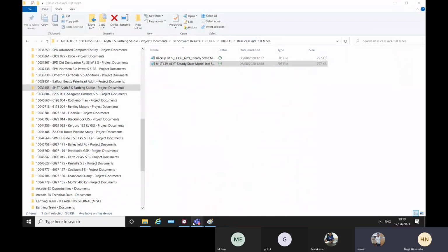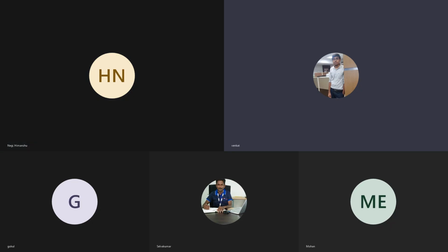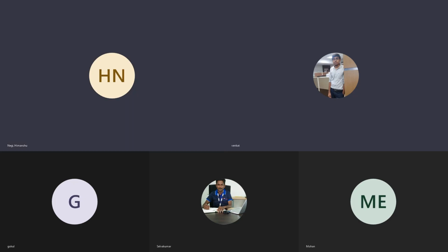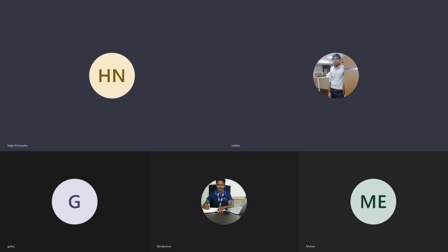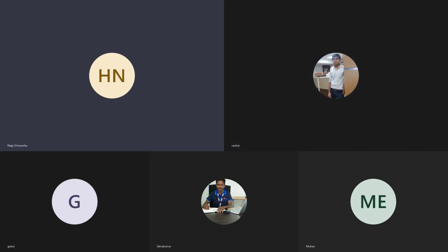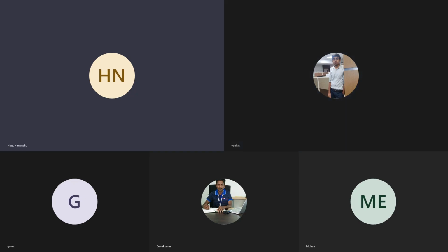But this is all about GIS from the earthing side. It is all for the safety purpose, right? Yes, safety purpose as well. And the dense mat I was showing you, the intention was that you need to put that dense mat below the GIS. And who tells you that? It is basically the manufacturer, not the owner, not the utility owner or the substation owner. It will be the guy who manufactured that GIS, who supplies the GIS.